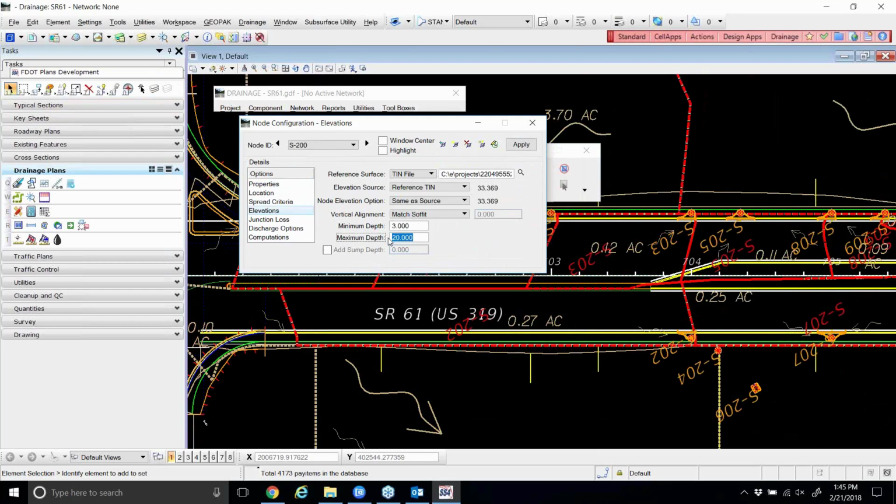So this pipe here that's shown in the middle of page 5.5, the smallest size that would ever calculate and make the pipe would be 1.5 feet, so that's 18 inches. The biggest it would ever try and make this pipe would be 60 inches. And that's like the pipe envelope. That's the size range that the pipe can take as you analyze and process the system.